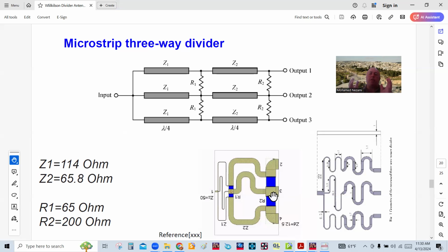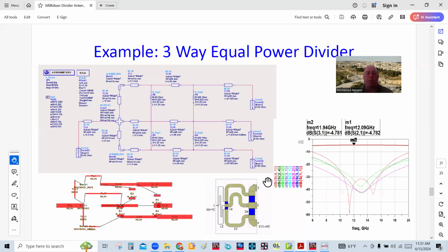So it's very, very important, of course, to get physically all the outputs and inputs the same length, so that there is no differential phase or differential time delay between the outputs, okay, relatively between the outputs. So you always need to meander, for instance, the middle line, to get the outputs to be all lined up, okay? And in this case, of course, you end up with 4 surface mount resistors. The design equations for these are well documented in the references, so you can just Google on IEEE publications, a 3-way splitter, and you get a whole summary of that.